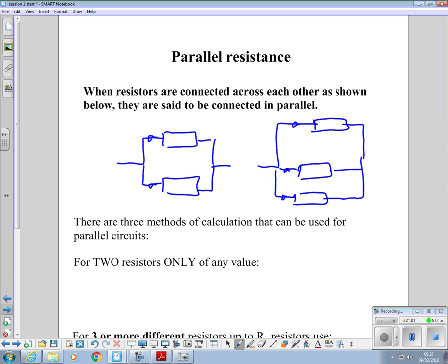What do you think happens to the overall resistance of that circuit because there's 2 resistors? It's like the water's got 2 different ways to go. So there's overall less resistance, because it's got 2 different paths it can take. So the route from there to there, for instance, if that's the direction the current's got to go through, overall the route is easier. It's like having 2 roads to go to the same place. The traffic's got more space to spread out in.